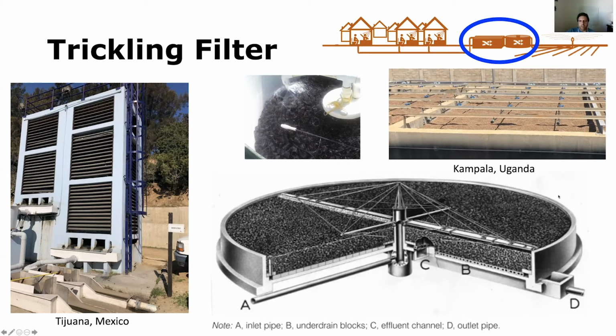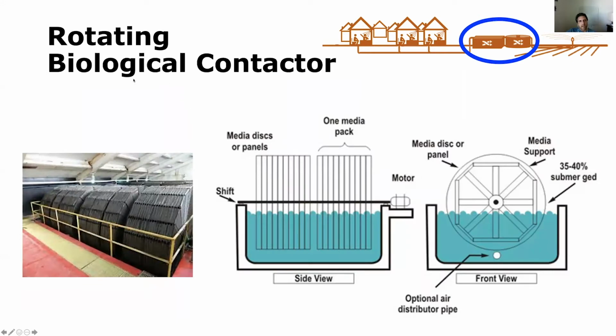All right, so another example of a small flows treatment system that is used in different contexts: the rotating biological contactor. Again, this is a forced aeration system, kind of like activated sludge. However, the difference is that instead of developing microbes that are growing in suspended growth, this system is optimized for the growth of microorganisms that form biofilms as attached growth.